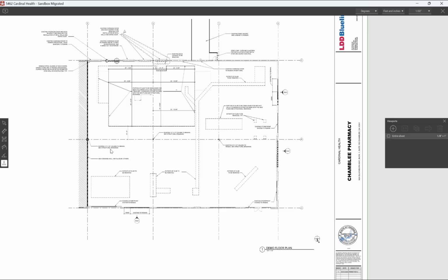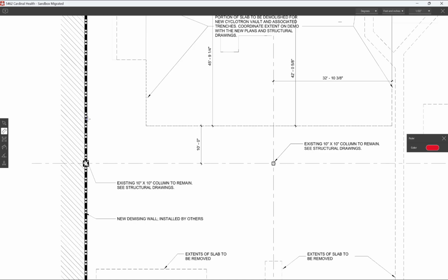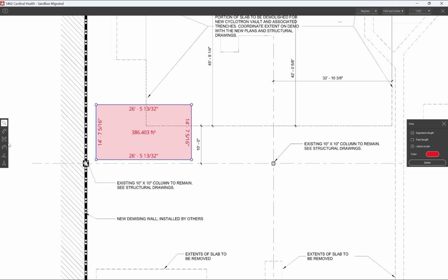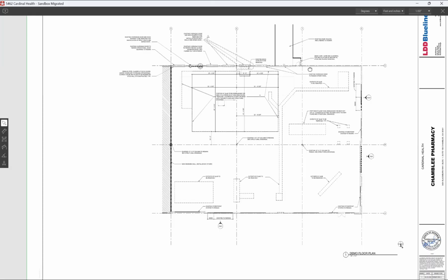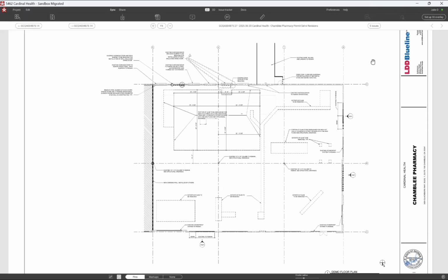Once that is done, you will be able to use the ruler tool. You can simply snap between 2 points and get the exact measurement. Now you can also view areas, very simple. You view polylines. You can connect to multiple points here. And the last one is going to be angles. And so this just allows you to view whatever angle it is you're making here. Go ahead and finish deleting these as they're not necessary for this, and go ahead and back out. And you will need to calibrate each sheet individually.